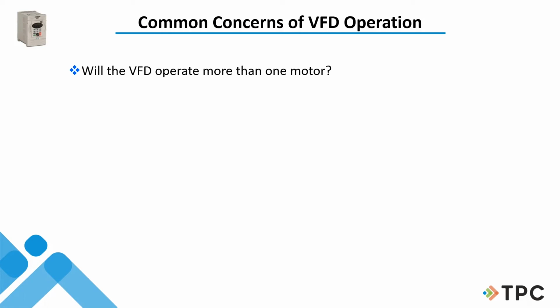Here, concerns for VFD operation. Many people put multiple motors on one drive. Can I do that? Well, yes, I can, as long as I understand that all those motors have to run the same speed. So when I turn it up, they're all going to go up, and when I turn it down, they're all going to go down. And the drive has to be capable of the total current of all the motors. So whether I'm putting 3 motors or 4 or 5, I have to know what the FLA on all those motors is, and I have to buy a drive big enough to handle that maximum current.